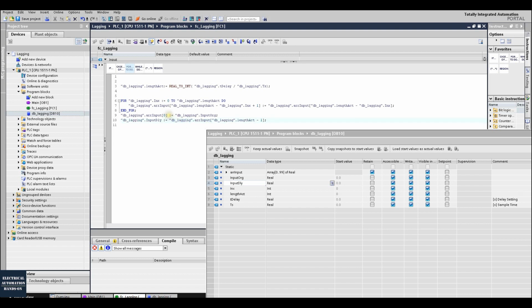Okay, as we can see here, 0 will be used to store the new data, and the last item of this buffer will then transfer this delayed result. This delayed result will be used as the real input for our transfer function.